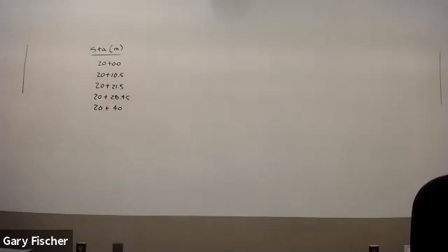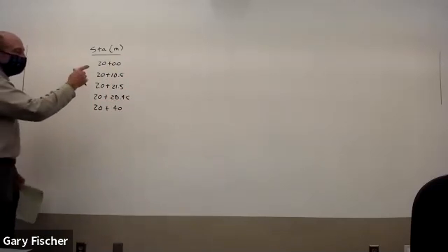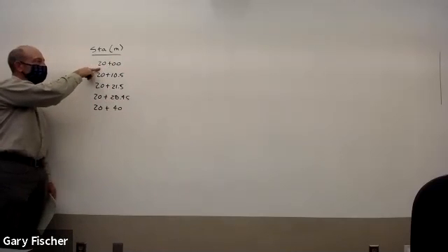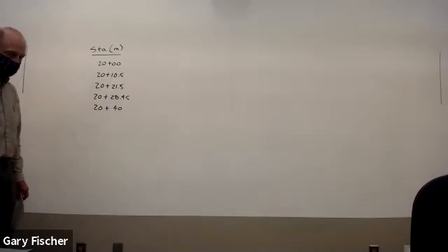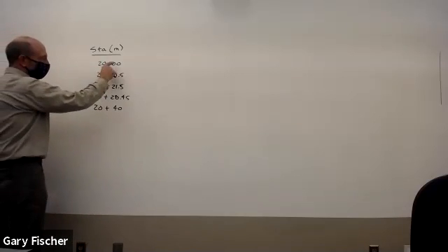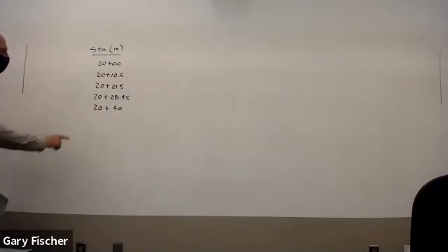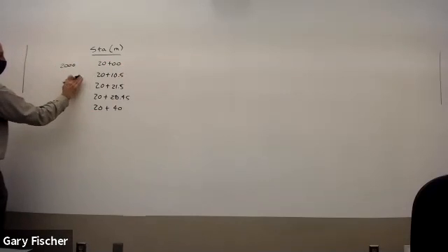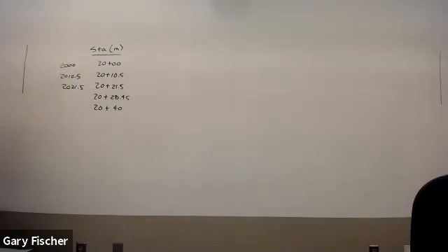These designations mean the number on the left side of the plus sign is hundreds of feet, and the number on the right side is feet. So the actual number for this would be 2,000 feet. For the next one, it would be 2,010.5 feet, 2,021.5, etc. Why do they write it like that? That's a good question. I don't really know why. It's the designation that they identified for it.